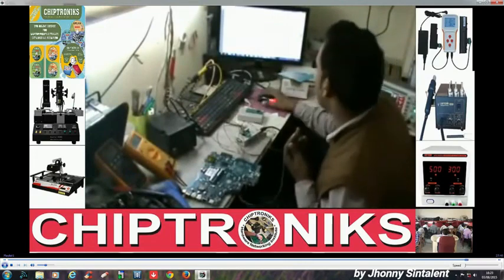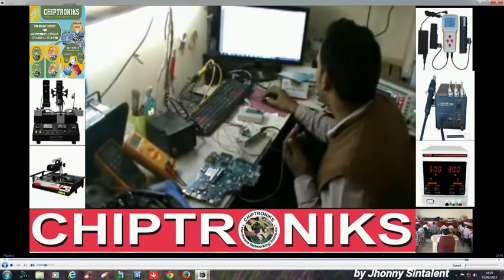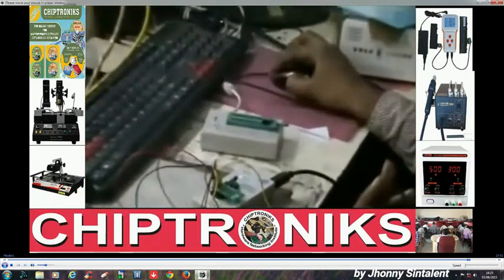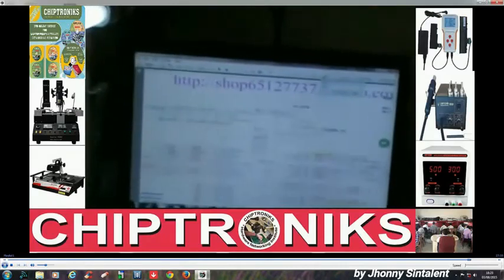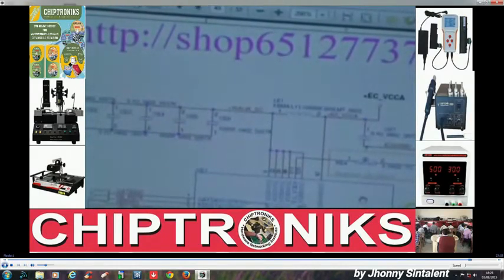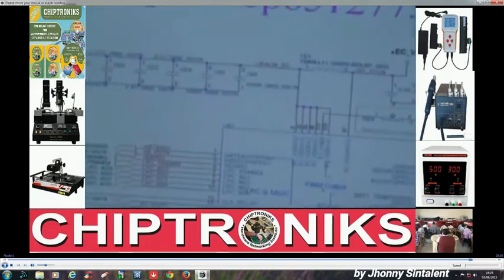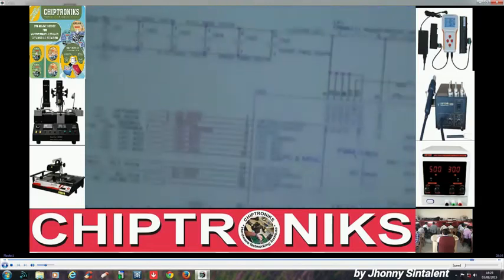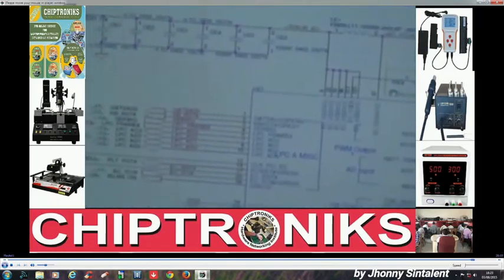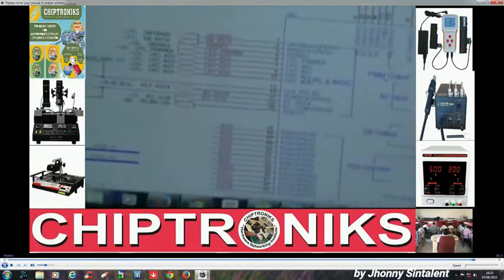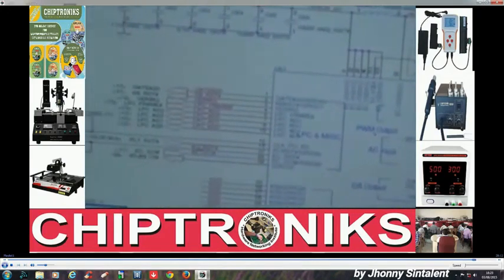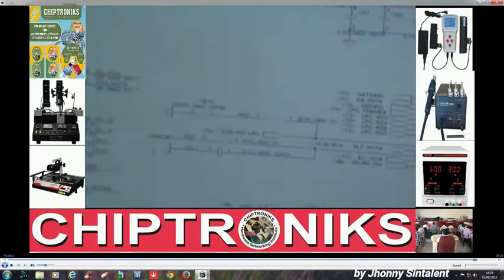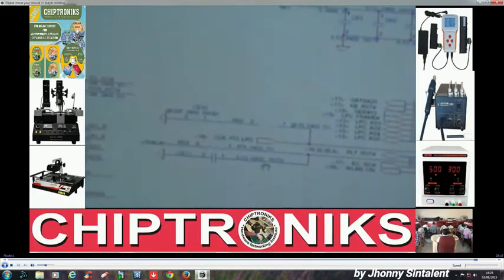By this we are supplying the supply, reset and clock. You see over here, 39. We go back to page number 40. Here all these supplies are given, EC reset. You can see how to operate this IO controller. 3 things: supply, reset and clock. Supply is already provided, 3.3 volt. The regulator will supply the 3.3 supply over here, and reset, you can see EC reset, which is also coming from the 3VLW. So reset is also there, supply is also there, clock is there.